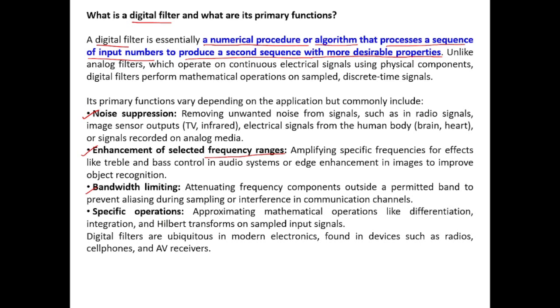We identify those peaks and find the time period between the two peaks, and from that time period we find the frequency, and from there we can say what the heart rate is. So band limiting can help us in extracting some information that is not possible in the normal time domain.